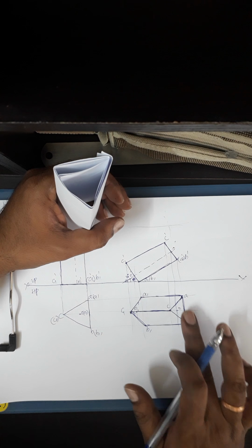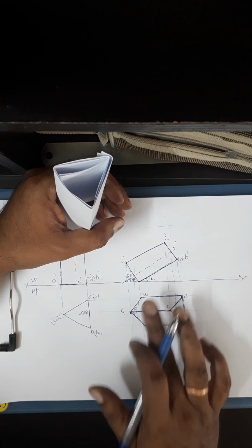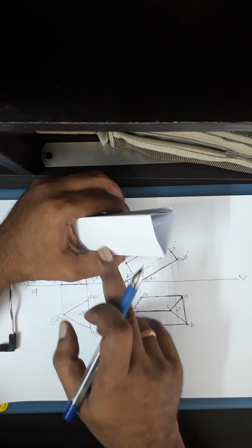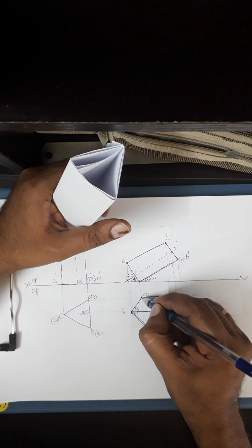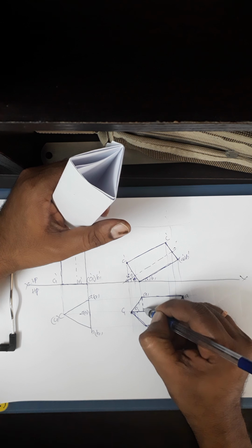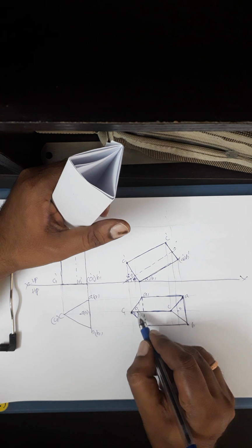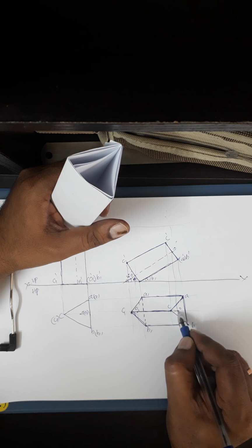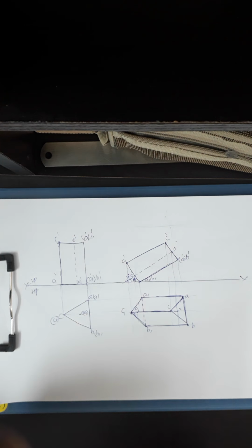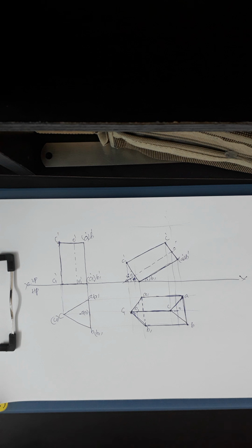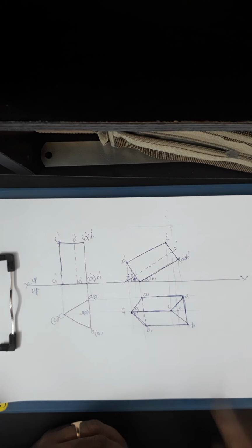Once you complete this, this is our surface, this is one more surface, so there should not be any dark line passing through those surfaces because you're not going to have any edges on the surface, okay? In that case, A1, B1 is not joined, so that will be a dotted line. That becomes the invisible edge. So draw with a dotted line, right? Okay. The axis is overlapping here. Only to this you can see, so make that axis a big dash and a small dash only to this length, where you can mark, because that's not overlapping. You have to show that axis only for this length. This is the solution for that problem I mentioned, okay.